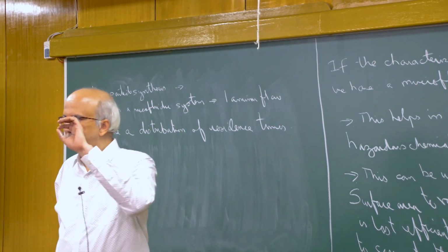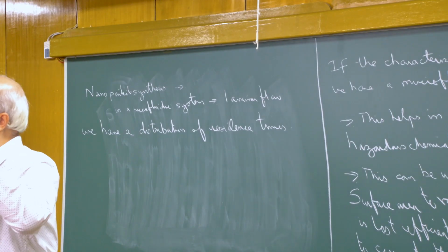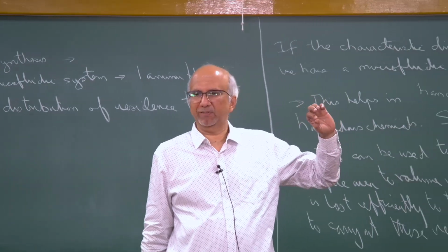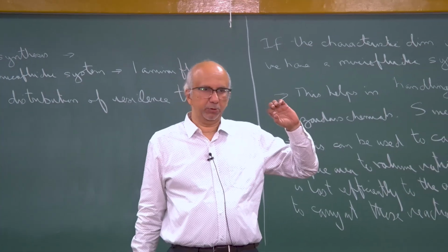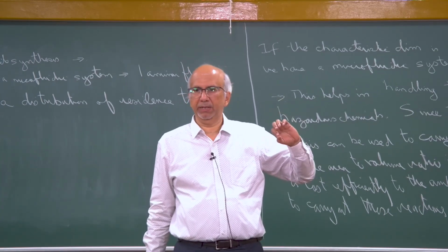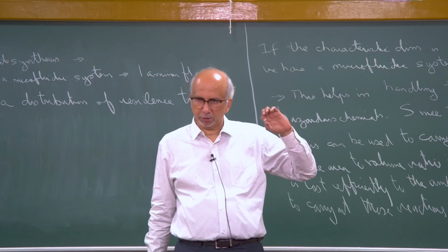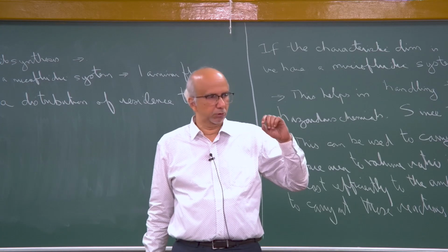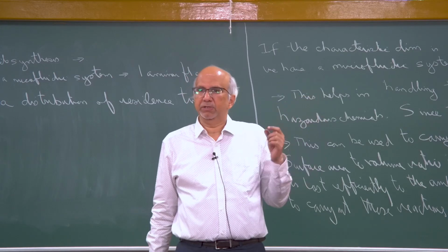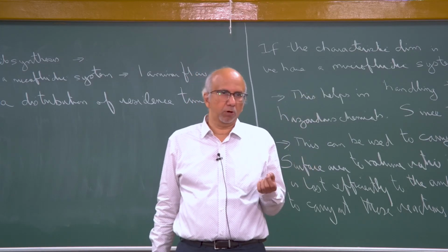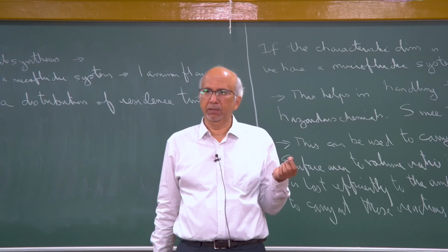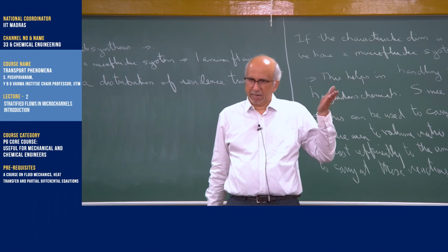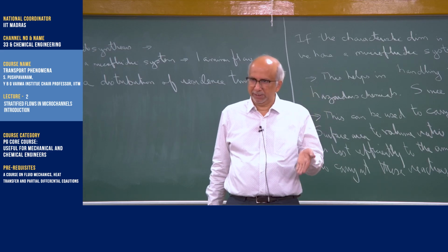which means the fluid element which is flowing through the middle is going to have a higher velocity. So, it is going to spend less time in the reactor, in your microfluidic channel, which is where the synthesis is happening. The fluid elements close to the wall are going to spend a larger time because the velocity is lower there; as you go closer to the wall, the velocity tends to 0.